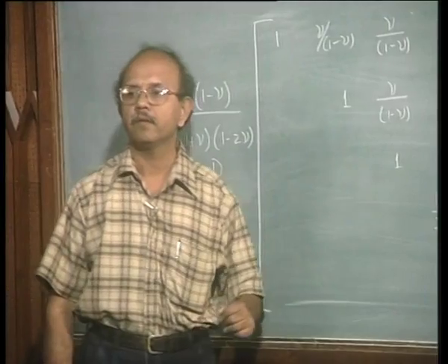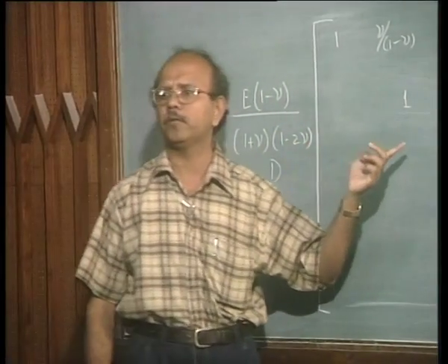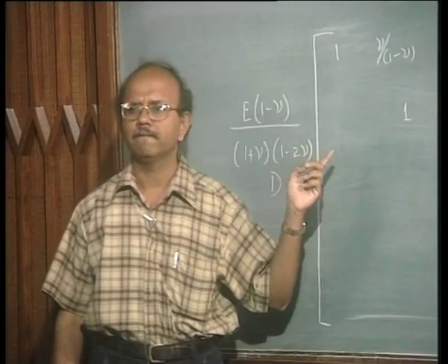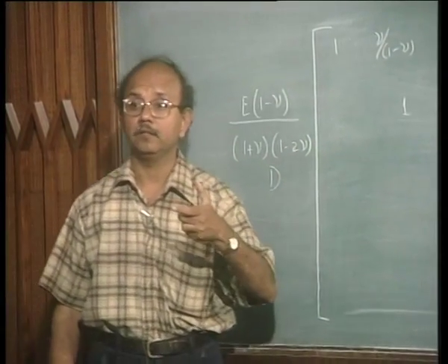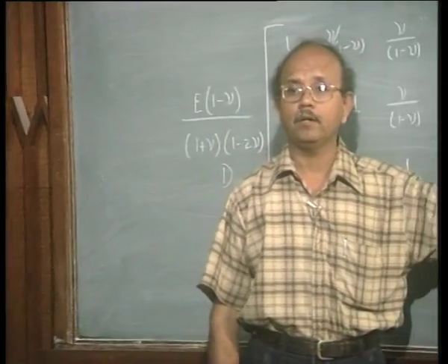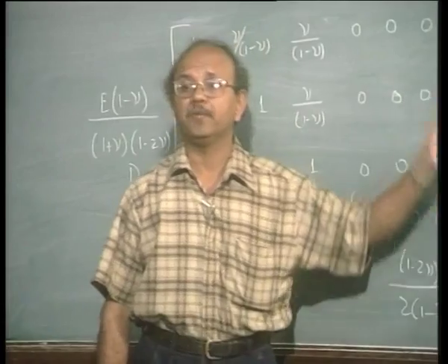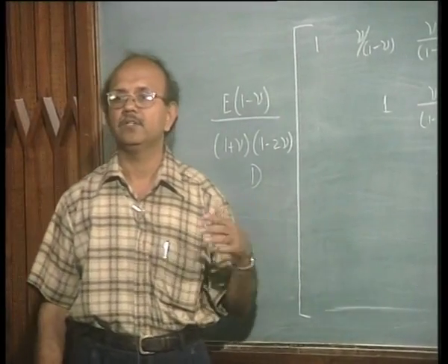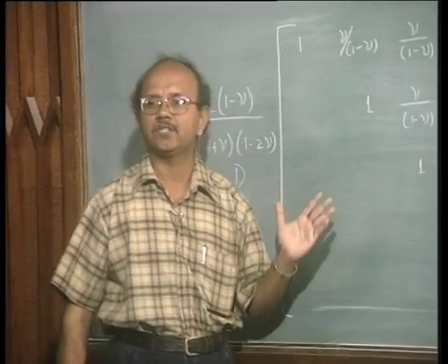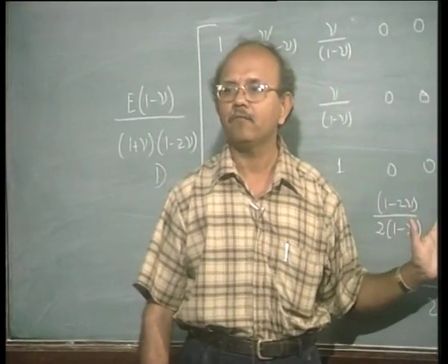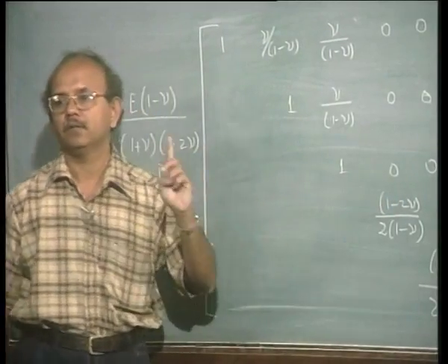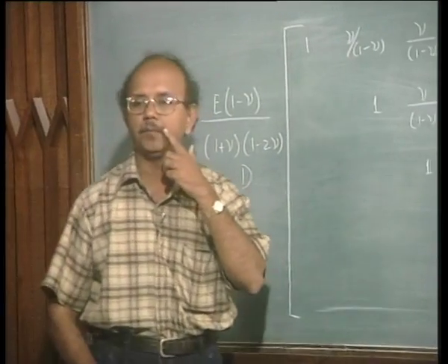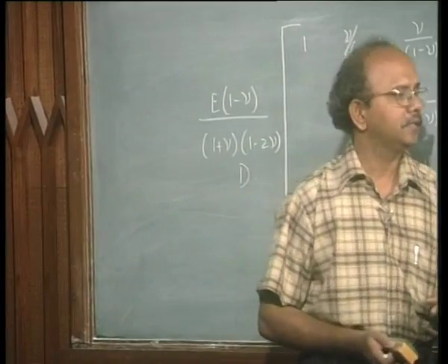Or C matrix. By the way, how many rows and columns will be there for plane stress? 3, okay, epsilon 1 1, epsilon 2 2, gamma 1 2. Epsilon 3 3 will not enter and will go separately because sigma 3 3 is equal to 0. Okay. So, you should be very clear about that as well, that for both plane stress and plane strain we are going to have only a 3 by 3 matrix, and that is simple algebra that I want you to write, and that matrix can be written as,